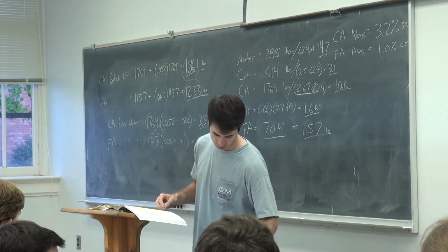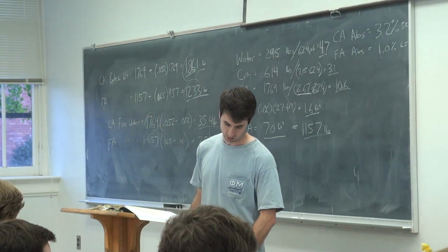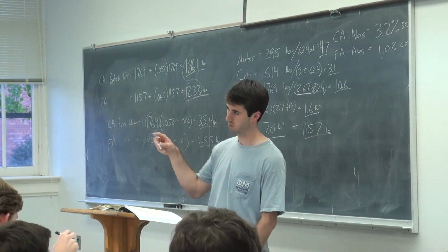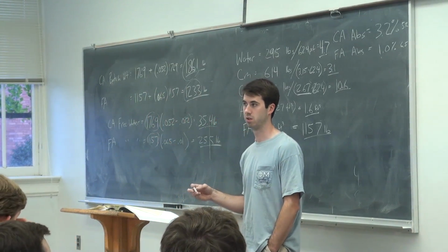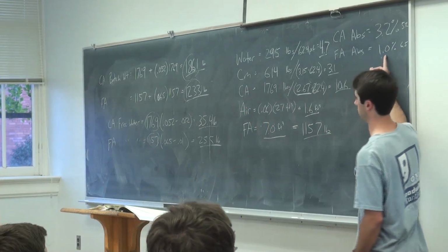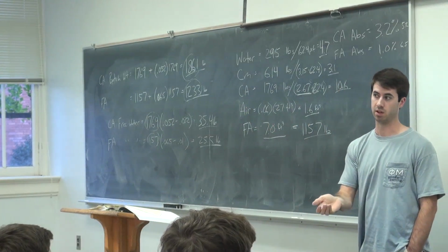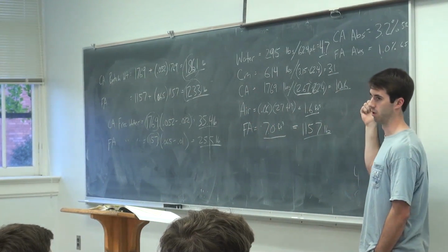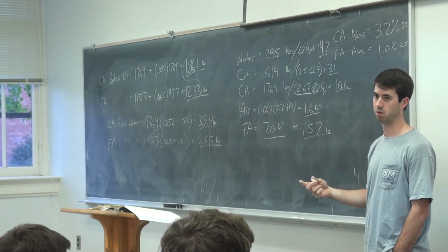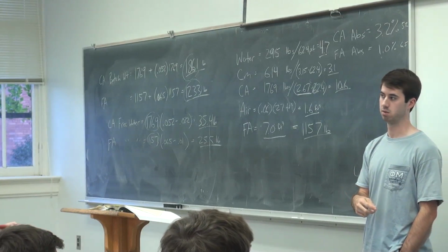The absorption is relative to the oven dry weight of the rock. Correct? So when you say it's got 1% absorption, that means if it's at SSD, you got 100 pounds of sand dry, you're now weighing 101 pounds, because 1% of that is water. Does that make sense? It's by weight and it's relative to the dry mass of the rock. Makes sense?